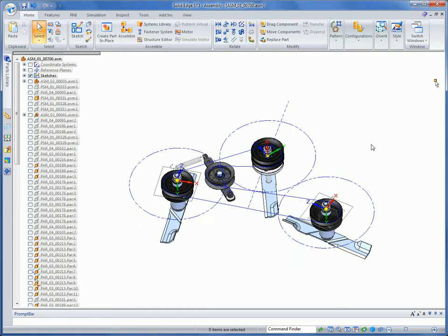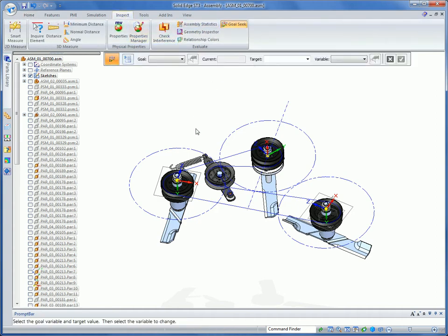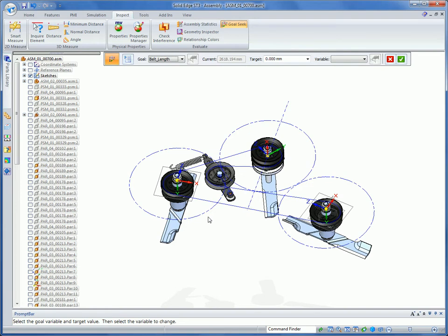But what I do need to worry about is that although I've got the blade diameters and the width of cut defined, I need to make sure I have a belt that I can purchase the correct length of. So when I created the sketch for the belt, I took the perimeter and associated it to a parameter called belt length. That parameter is currently at 2618, and I want it to be 2650 millimeter.